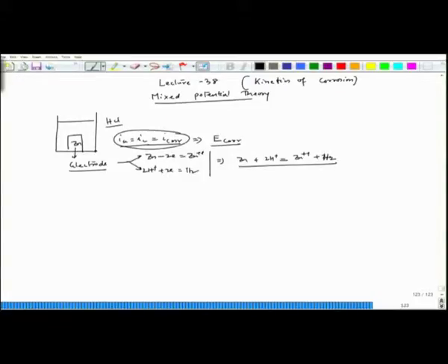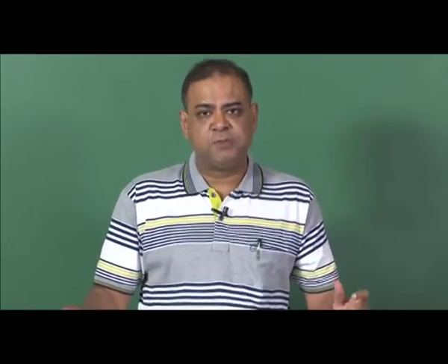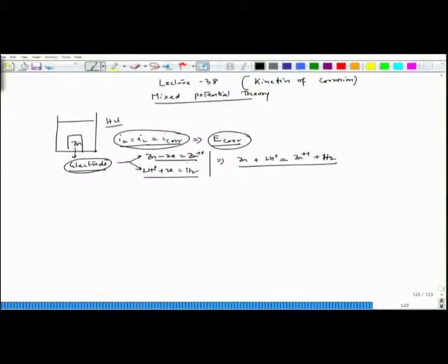And this electrode would achieve a unique mixed potential, which is not the same as the potential for the single redox reaction, the half-cell reaction. Each half-cell has its own reversible potential to begin with, and the electrode shifts from that potential to this E corrosion due to the combined reactions. So now we see the concept of I corrosion and E corrosion.